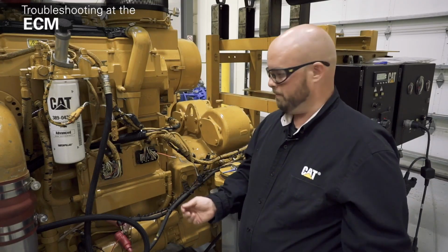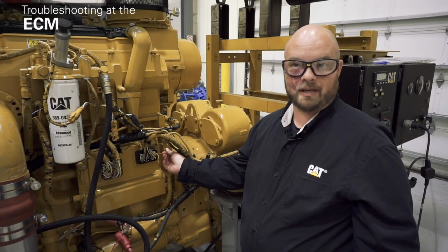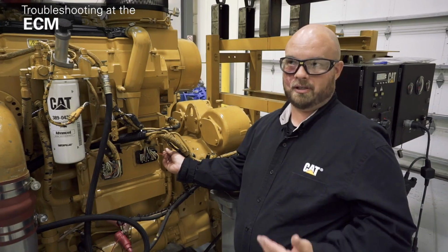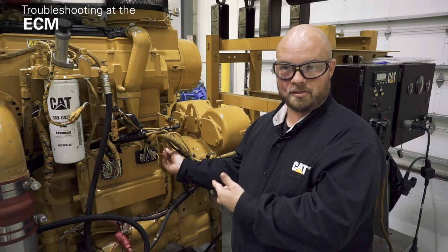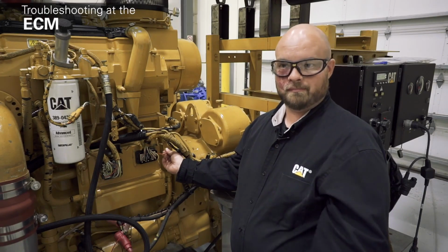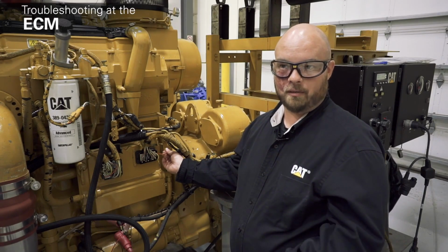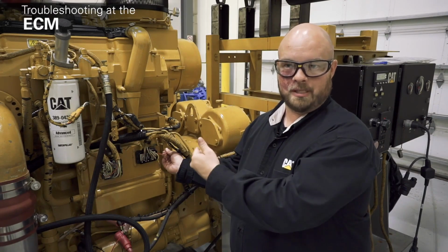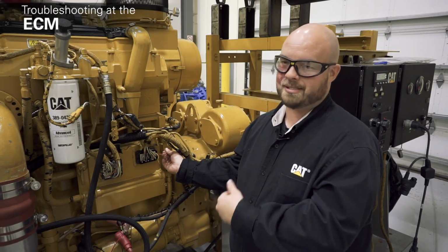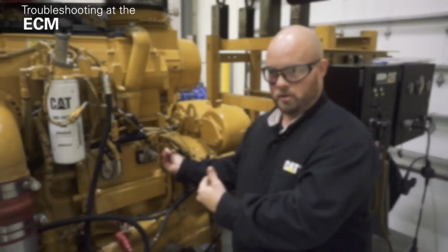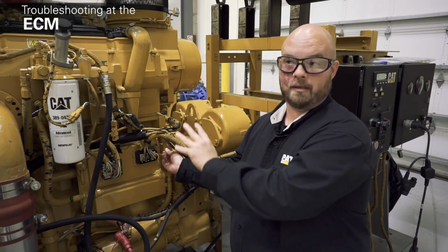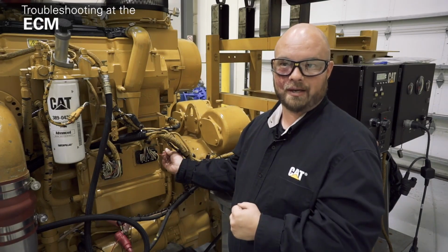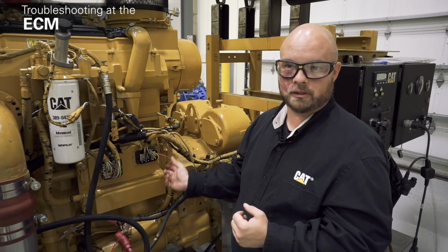So let's flip that around. If I've made my short circuit here at the ECM and I wait my several seconds, but I still have a -3 code, right? Voltage above normal, even though I'm shorting out that circuit on the ECM, well, this is kind of a rare occurrence, but that would tell me that something inside the ECM is open circuited, okay? We can't go inside the ECM, we can't troubleshoot the internals of the ECM. Try to replace the ECM or put on a test ECM, and if that fixes the problem, I always want to validate and put back the old ECM on. My problem should immediately come back again, and that's a real good procedure for replacing the ECM.